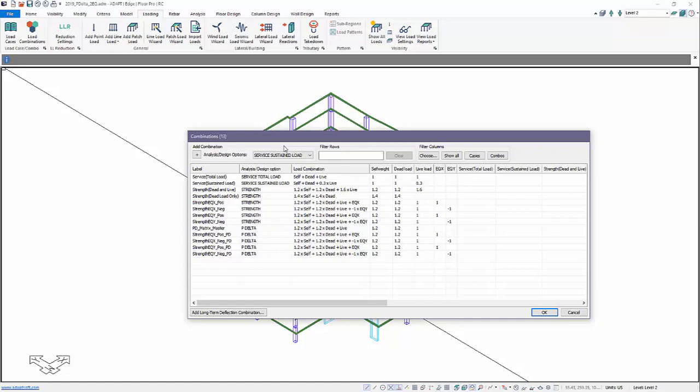Now in this example, I want to create a batch solution. So what we're going to do is set up a combination we call P-delta matrix master, and here we're going to define the gravity load cases that we want to include for the production of a geometric stiffness matrix. That matrix will then be used for subsequent P-delta combinations that include identical load factors in terms of gravity. We also have factors for EQX 1, -1, 1, -1, but those will just be additional load cases producing a result for that particular combination.